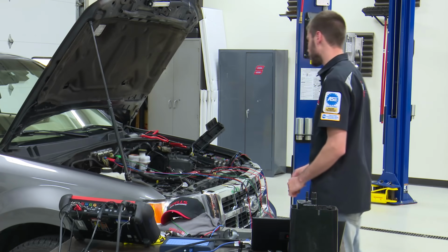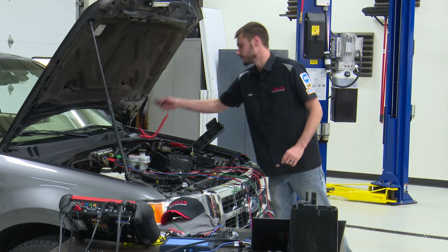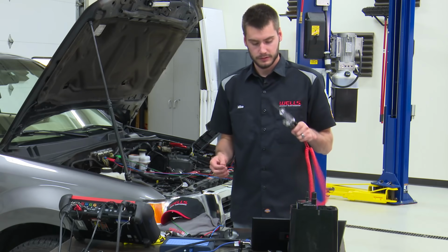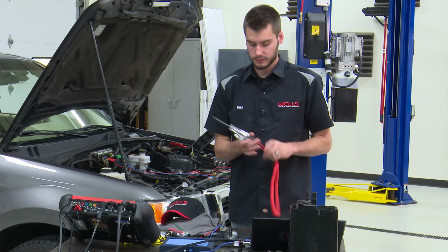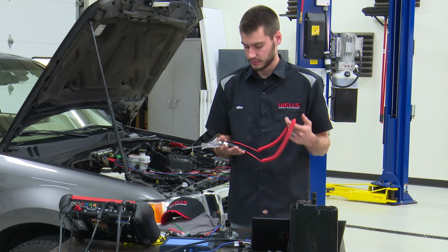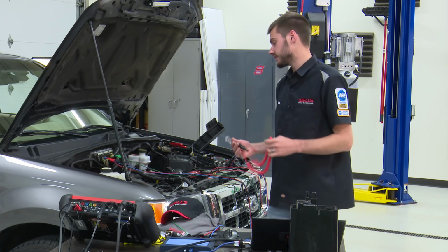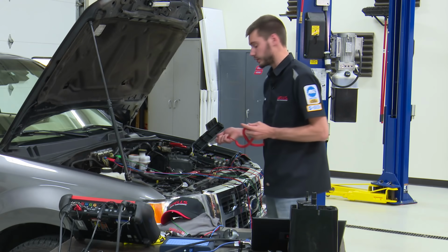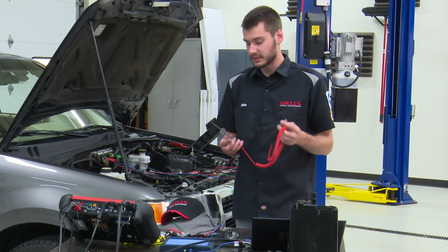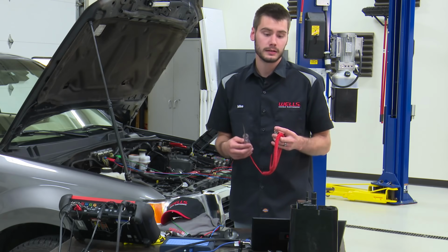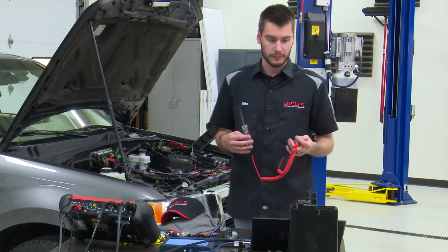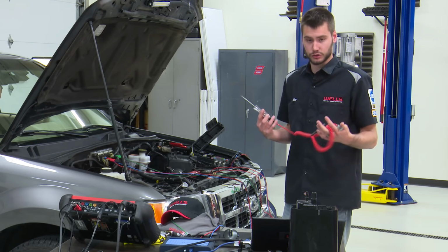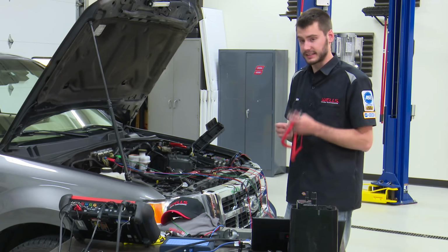And then when it comes to circuit checking, testing your vent and purge solenoids, when they're grounded by the computer, this thing kind of reigns supreme, right? An incandescent test light is a small amount of load. It's going to be less load than the solenoid would put on the system, but it's enough that it could maybe weasel out those problems where you're still getting 12 volts, but you're not getting the current behind it to actually do anything. A test light will help you with that.